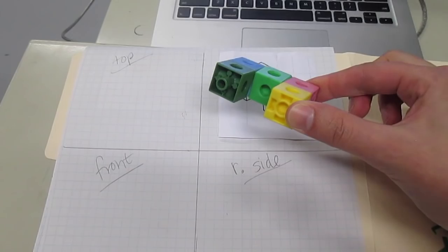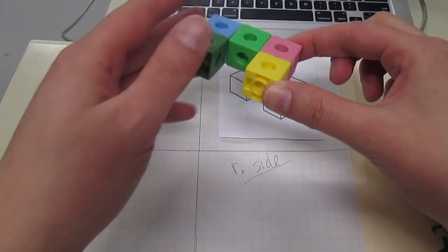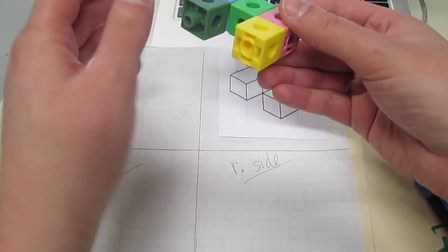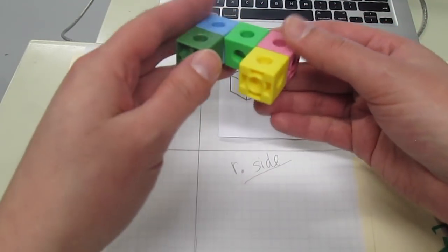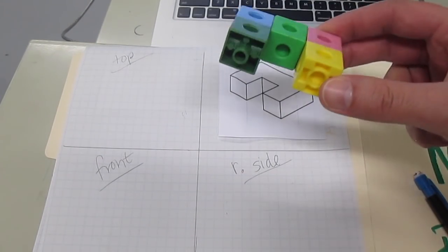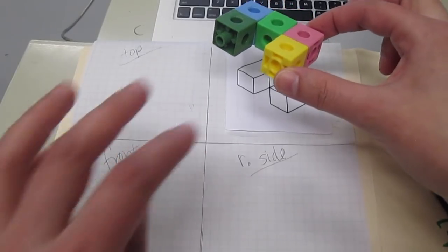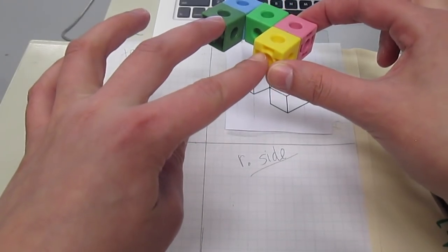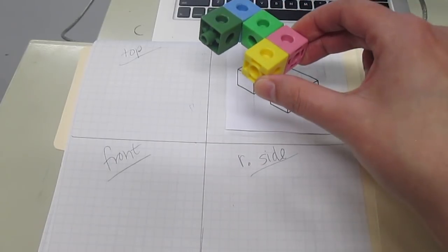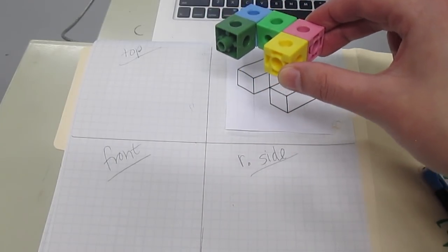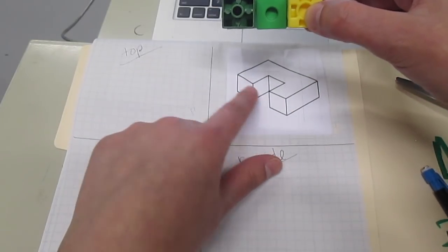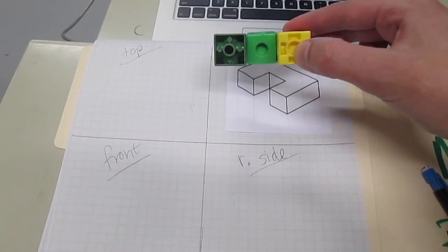Okay, in the isometric view you see 3 faces. You see the top, the right, and the front. So remember the front is off to the left, top, right. This should help you as you manipulate or change your views. So in isometric, the front view is off to the left. If we start with the front view, we would position it like that. So you go from isometric, the front view is off to the left here. So this is the front view, okay?